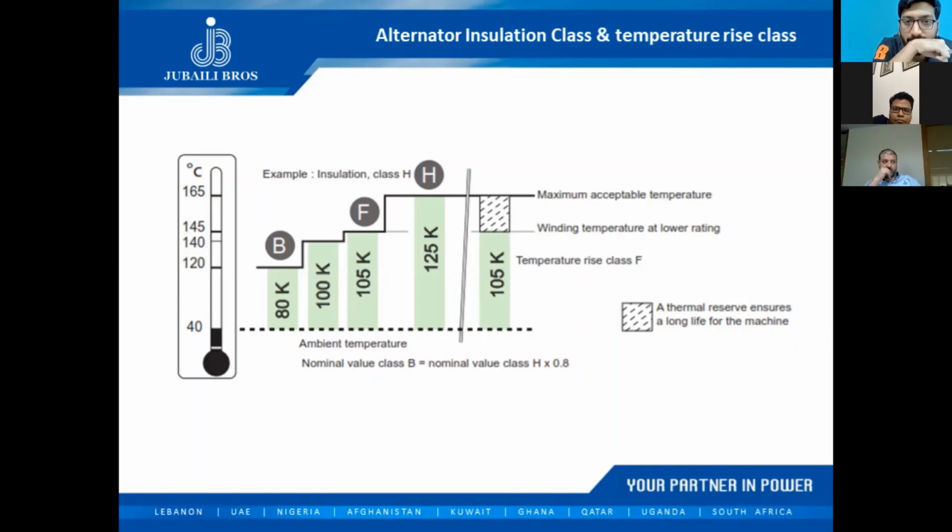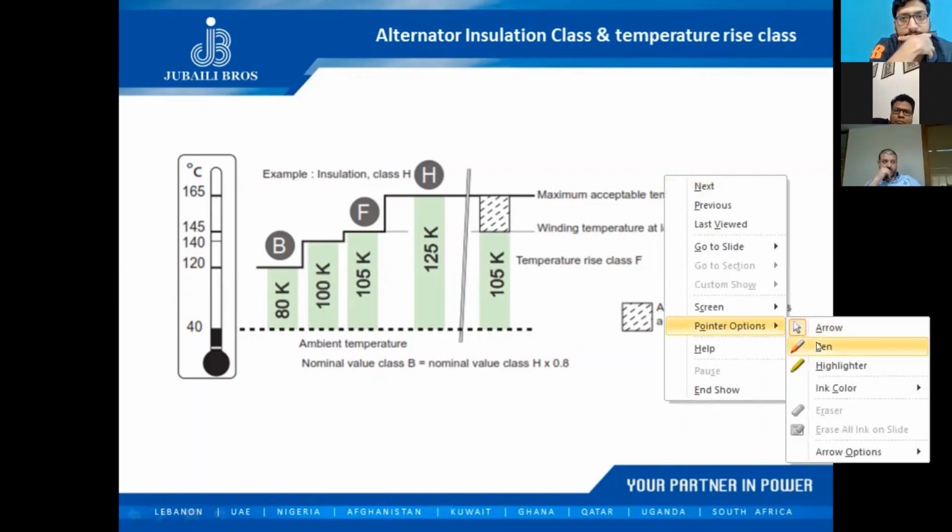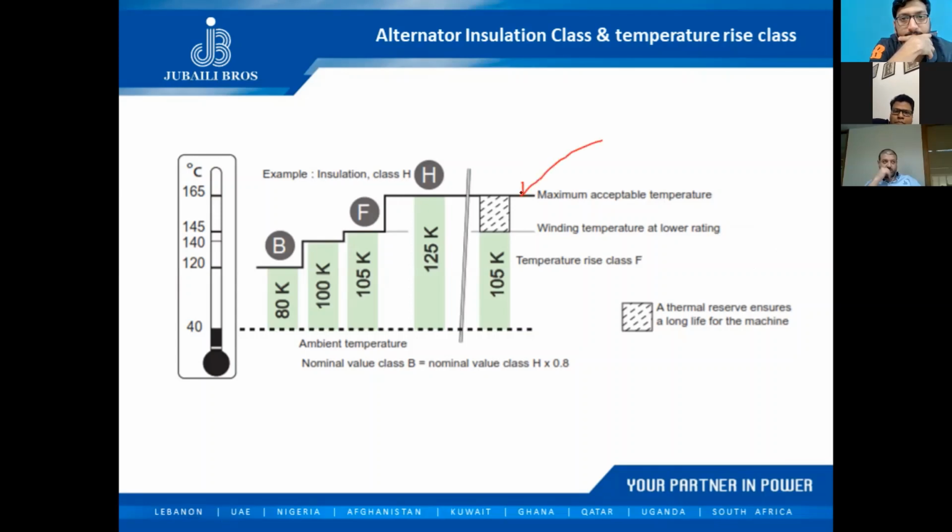So we have different insulation classes, H, F, and B. And by the way, this applies to motors as well, in motor applications rather than in alternator applications, because it's the same idea, copper windings that are insulated, okay? So class H, being the highest insulation class available commercially, okay? This chart tells me, you see this black line, guys, that looks like a staircase. Let me just try and trace this black line here. Okay, so this line defines my insulation class.